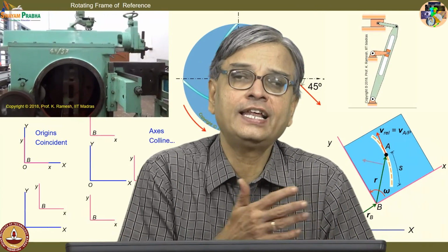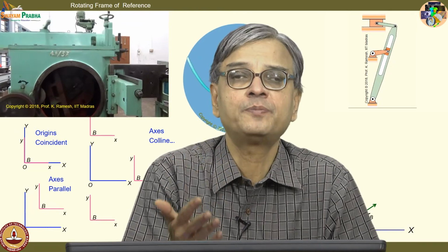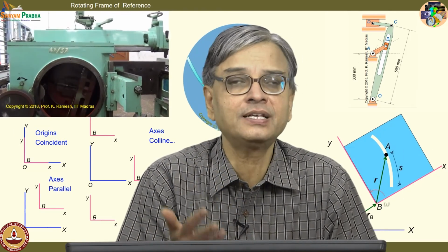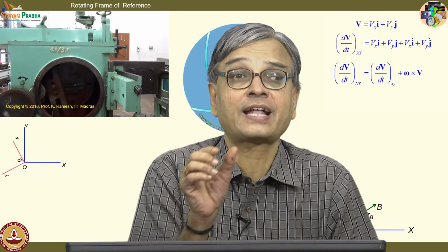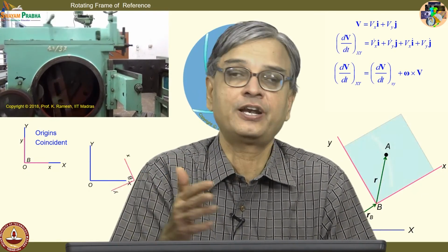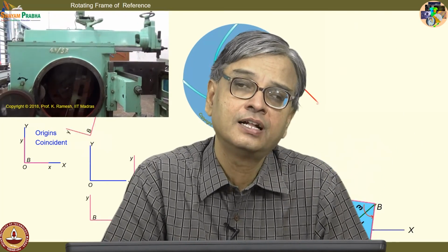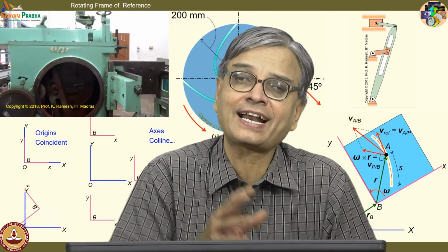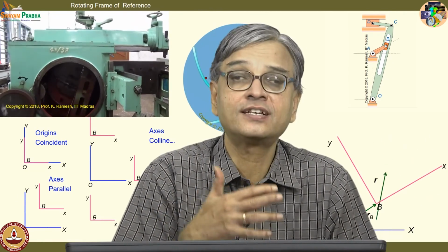And once you finally get this, the expression can be written down as VA equal to VB plus VA with respect to B and AA equal to AB plus AA with respect to B. These relative quantities can have more number of terms depending on whether you are finding out the velocity or the acceleration. And we also reviewed the two problems we have done earlier, so that you get a clarity what is happening to the rotating frame of reference, what is that you perceive.